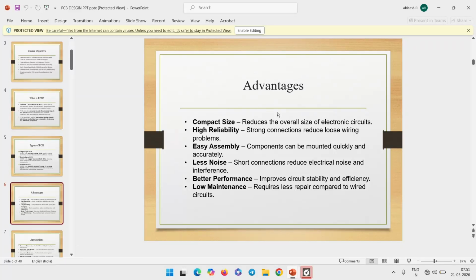Due to that, the markings, which means R1 is resistor 1, R2 is resistor 2, C1 and C2 are capacitors 1 and 2, are placed on the board, which is called the overlay or reference designator. Mention that word, reference designator. Reference designator means if you have 10 resistors, each one has a label R1, R2, R3, R4.